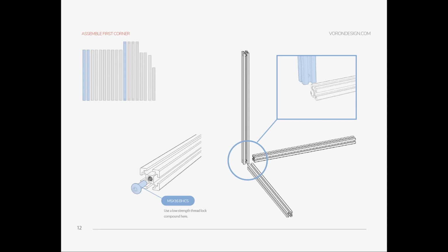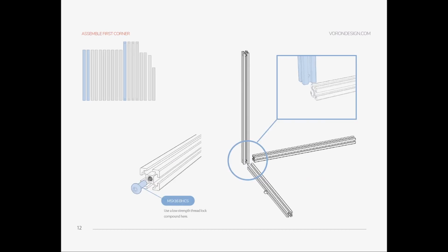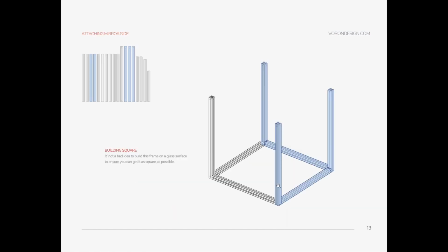You can use a big mirror, big glass, or countersink. But keep in mind that it's not rocket science. I mean, it will be a tiny bit out of square, but it's not a problem. It's not a big deal. As long as the difference between these diagonal measurements is under 2 mm, it's okay, the developer team says, but I try to keep it under 1 mm. So like I said, just do your best and try to keep this difference under 2 mm.